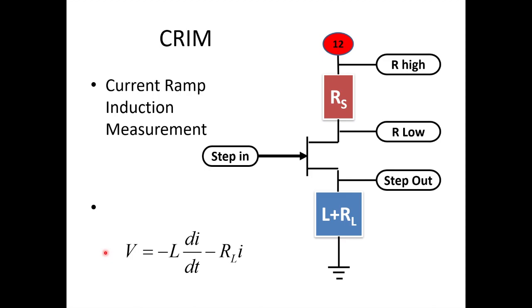And there, again, to people that aren't going to become Patreon members, there's other things you need here. You need a protection diode here, like we described before. You're going to need protection on here to prevent electrostatic damage of this. You're also going to need termination resistors. And you probably need a lot of capacitance up here because you want to keep this voltage constant as the current ramps. So you need a whole lot of capacitance. There's probably some other things I forgot, but normal engineering techniques are for those things.